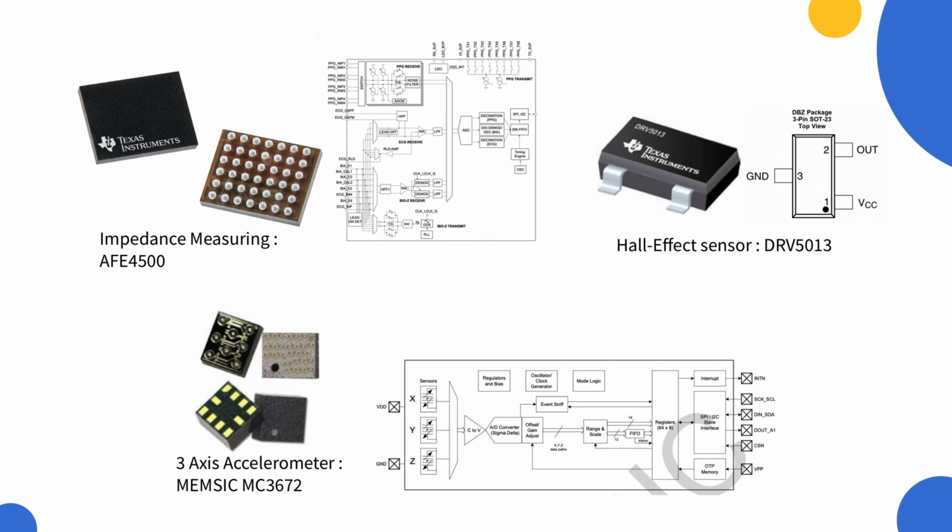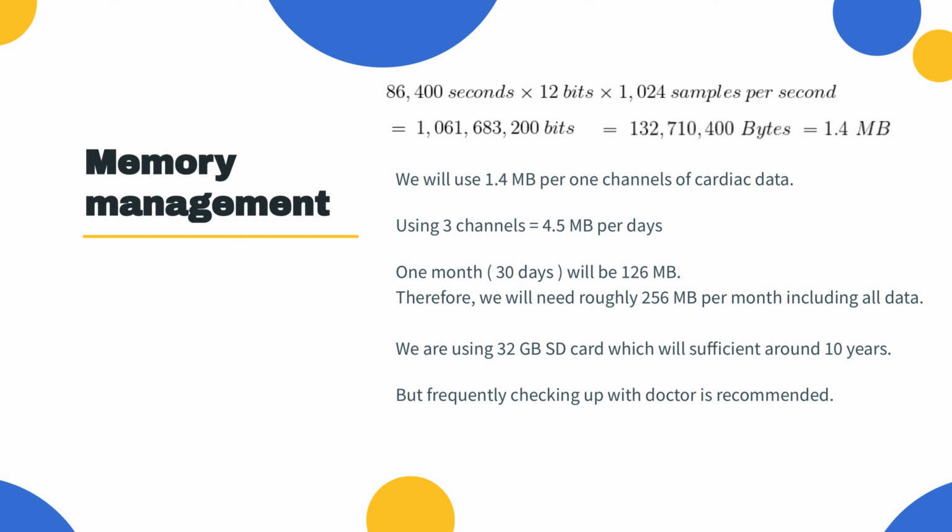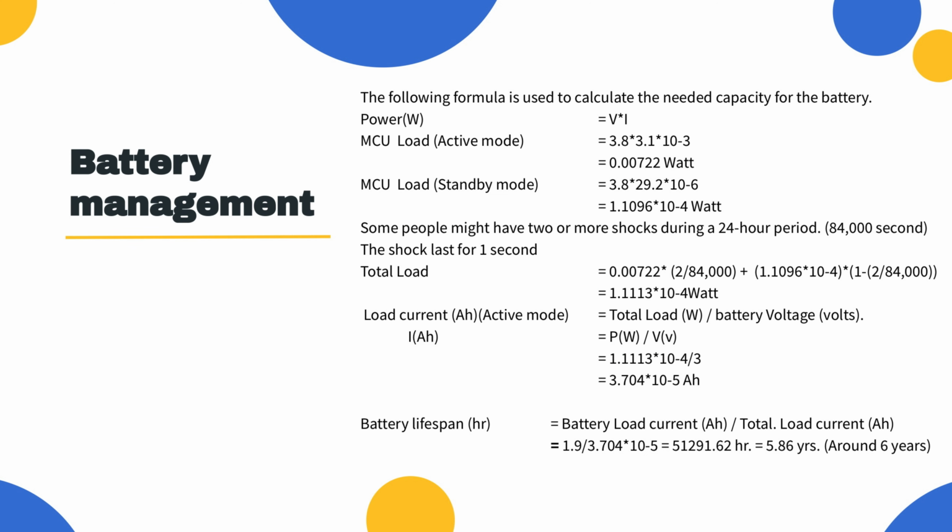data to the MCU. And for the memory management, in one day, we will use 1.4 megabytes per channel. So in 1 month, it takes around 256 megabytes. With our 32 gigabyte SD card, it will be sufficient for around 10 years, but checking up frequently is recommended. We calculate the battery lifespan. If a patient has 2 shocks during 24 hours every day, the battery will be able to supply the operation